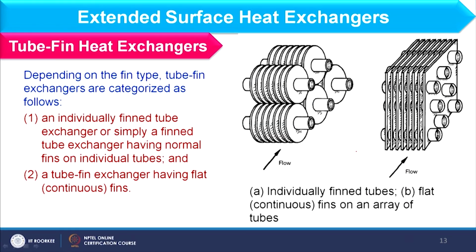Now if we focus on this schematic, here we have the tube fins. If I consider this image, here we have this tube, inside this tube fluid will move, and over this tube we have this disc type of fins. Because of this disc type of fins, the shape of these fins is tube type, that is why it is called the tube fin, and it is attached over the tube. It is like when you put CDs on a tube side by side, so it is this type of structure, and this we call individually finned tubes.